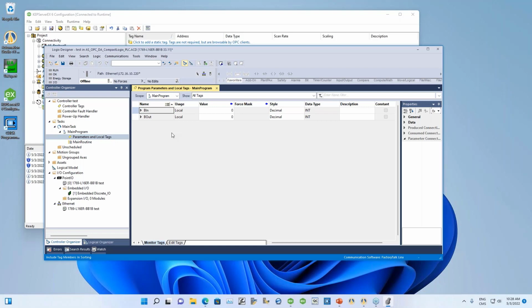The reason is that because I'm going to be using OPC, the PLC in the scan will always refresh the I/O based on how they are physically. And I don't want that, because all the inputs will come from Automation Studio. There is nothing connected, no real machine connected to my logic. So I have to do my logic using the internal registers. Later, after we do the validation, I'll show you it's very easy. Once we've validated the logic, we can get the values coming from the input and output and map and transfer the information to the input and output cards and make the program run on a real machine. We're going to do that part once we do the simulation and the validation of the program.